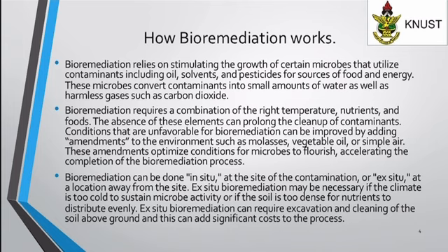The bioremediation can be done at the site of the contamination or ex situ, at a location away from the site. Ex situ bioremediation may be necessary if the climate is too cold to sustain microbe activity or if the soil is too dense for nutrients to distribute evenly.